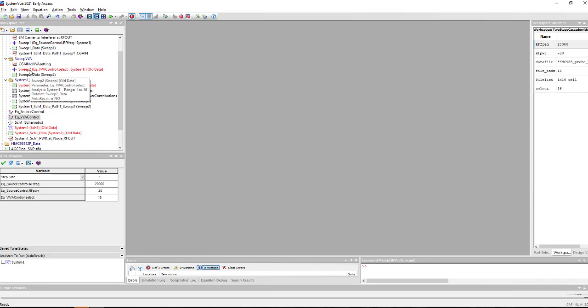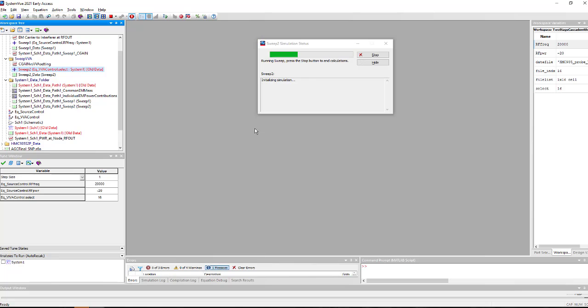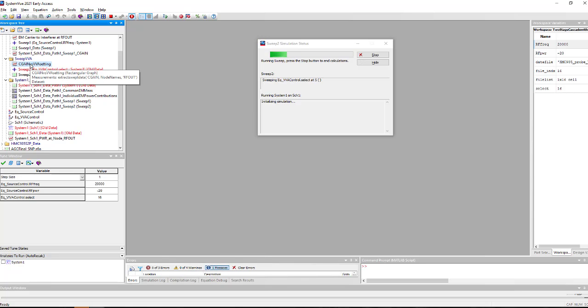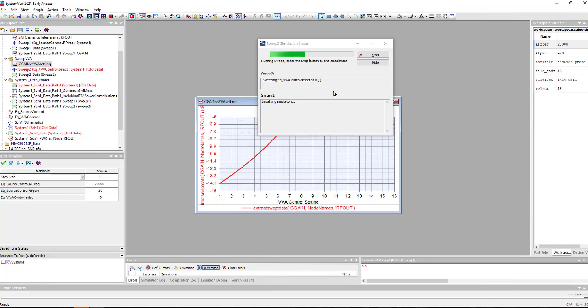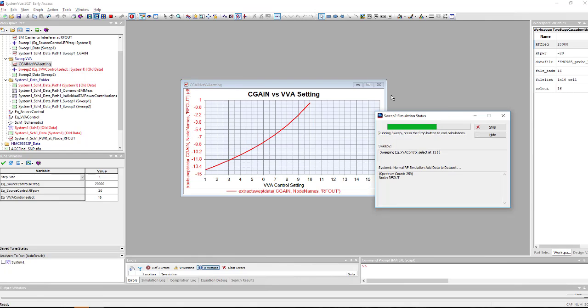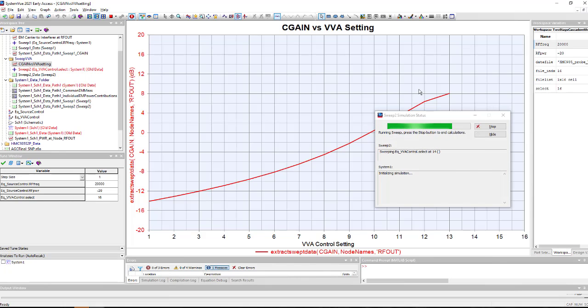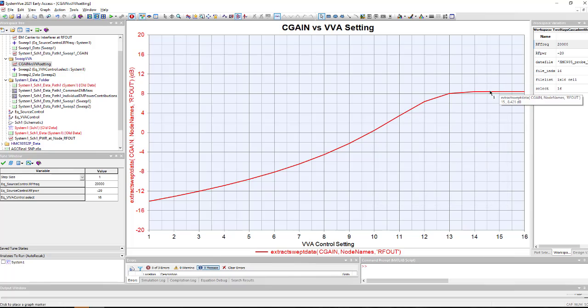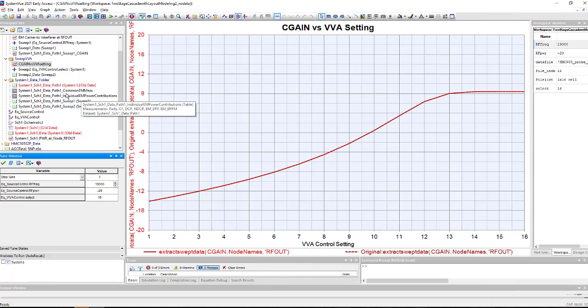So it allows us to run sweeps here versus our gain control setting and look at the actual conversion gain at a given frequency here. This is using the old design, and you can see we're lacking some max gain here at the output, resulting in lower max output power. That's because of some of the poor performance at this frequency. Then run it at a different frequency here.